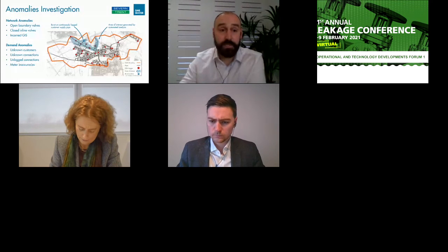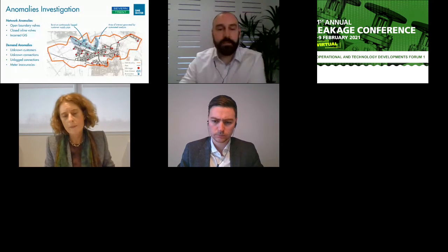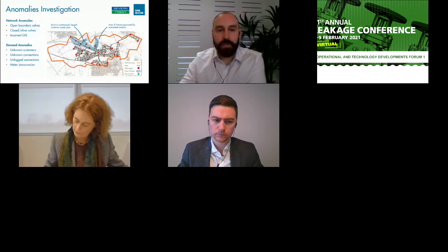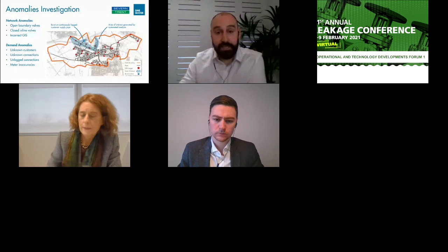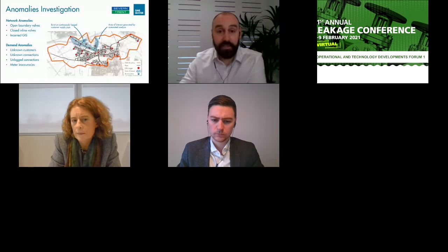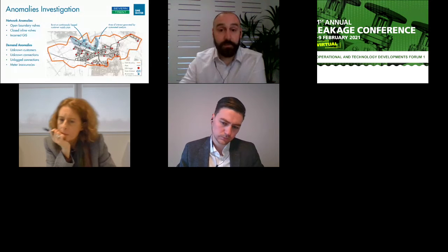Similarly, in terms of demand anomalies, we come across a lot of, at one extreme, unknown customers. So people who are just not represented in the system. We're taking water, whether that's illegally from standpipes or otherwise. But more commonly, you've got a known customer, but actually they've got a second connection that you're just not aware of on your GIS because you've mapped what's there. You've also potentially got unlocked connections. So maybe there's two connections in there, one's metered, one's not. Or also you've potentially got meter inaccuracies happening on the network.